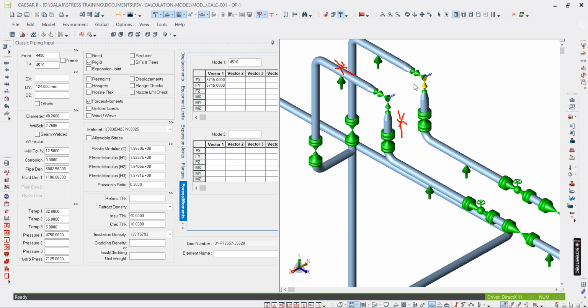Why we have to use it like this is because the reaction forces are there. In order to accommodate the reaction force, we need to design the support accordingly, because your forces will be transferred to the supports only. So you need to design the support based on the reaction force. So you will have more loads in the axial direction. Axial means towards the pipe direction. And here also in the vertical direction you will have more loads. Since we have applied this reaction force in two directions, you have to remember at the inlet hold down support.